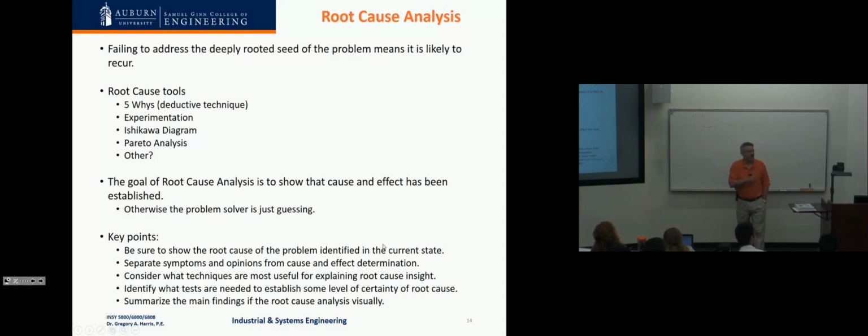Got a couple. So what does 5 why mean? You ask why 5 times and eventually you'll get to the root of the problem. Okay. Why? Because every why gets to a deeper step of the process. So say a part keeps having this defect. Yes, why is it having this defect? Well, this machine's having this problem. Why is the machine having this problem? Eventually, you have enough time to get to the root of the problem. Right. Good answer. Good answer.